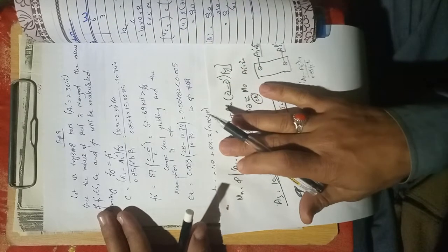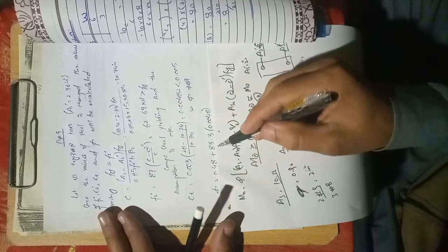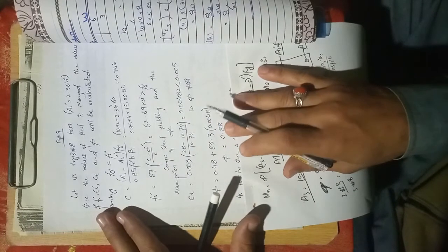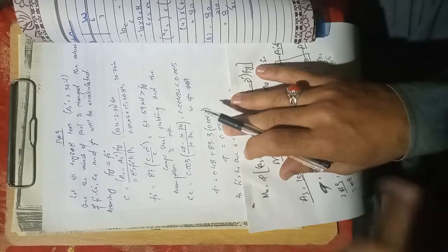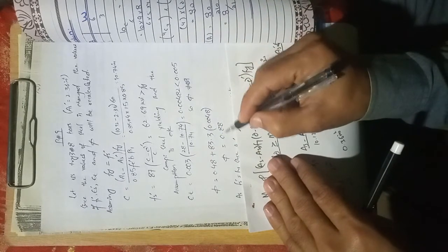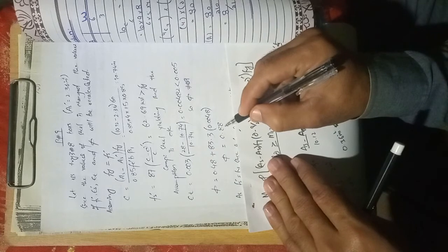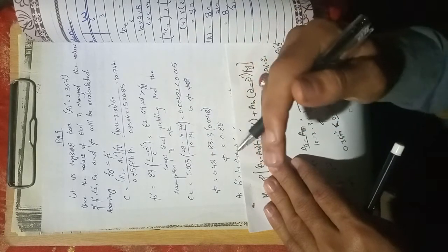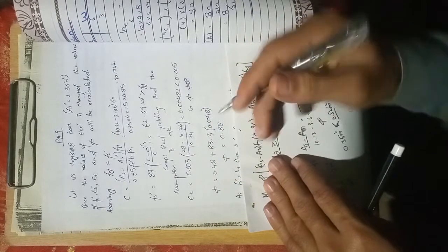So we have to find out the exact value from the same equation as we already used. So now this is 0.88. Now this is important that at the first stage, in the first trial, the phi value is 0.85. But here it is 0.88, which means the capacity is a little bit increased, right, by just 3%.